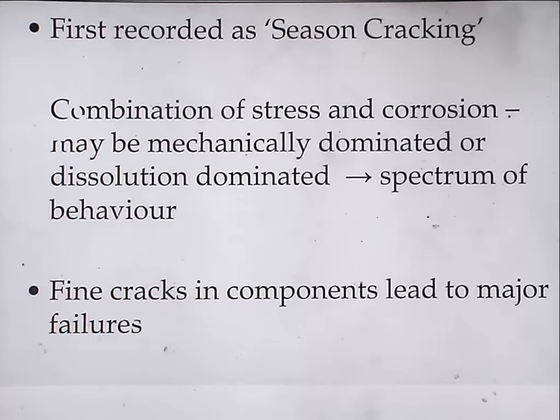So that's the origin. It was identified as a combination of the residual stress in the brass, because it's been heavily worked to make a thin tube, and the ammonia from the manure. And even today, in refrigeration systems that use copper alloys for piping, there are problems with ammonia and amine cracking of the copper pipes. So the problem's still with us in a way, in a slightly different form.